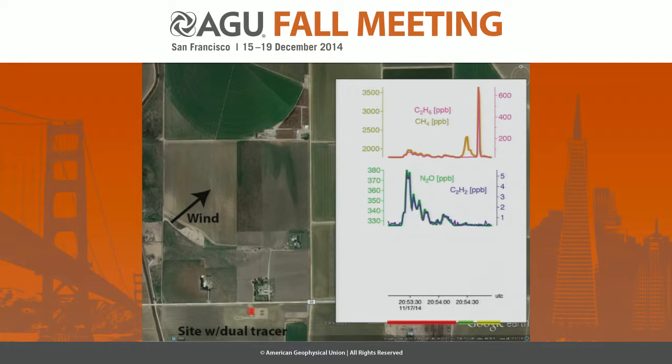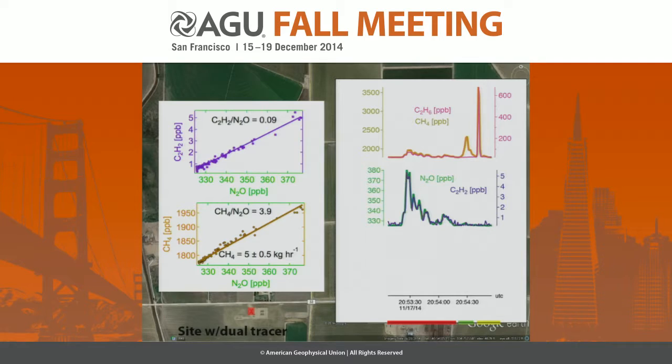We'll look at the tracer species. These are the two tracer compounds that we were using for that test. And look at that, they're right on top of one another. This is good. We check to make sure they're showing up in the ratio that we know we're releasing it at. They are. That gives us an internal check on what the test of that equivalent dispersion might be. It gives us almost an internal standard for what the error is. And then we see concomitant methane here.